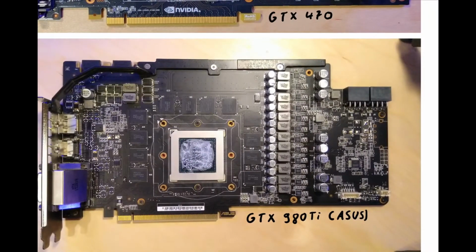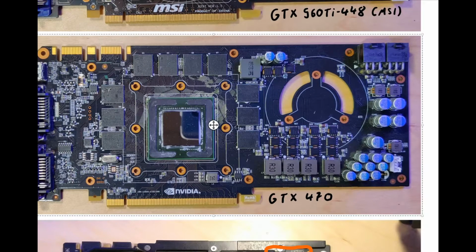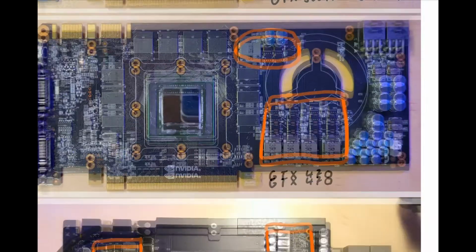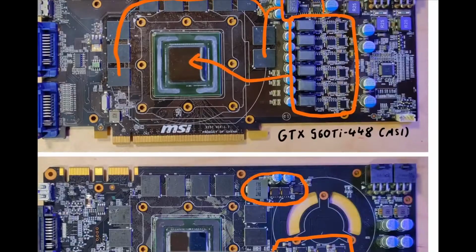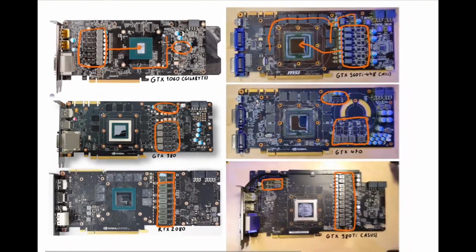Then over here we have again a really big vCore VRM, and then vMem is over here. If you can put vCore on the left, you can also put all the other VRMs on the left. Then over here again there is our little vMem, and then here's our big vCore VRM, which is again special because you can see it is 90 degrees rotated to the right or to the left, I don't remember how that works. So yeah, that's basically how VRMs can be laid out and how you can identify VRMs.